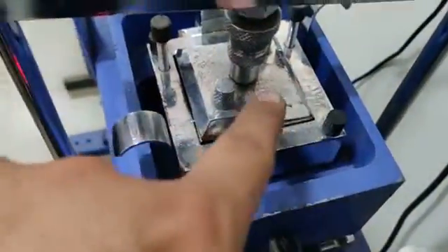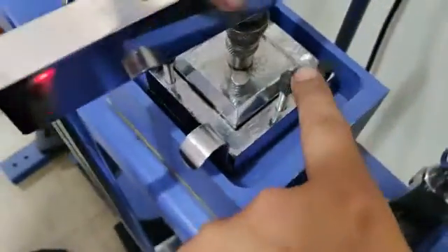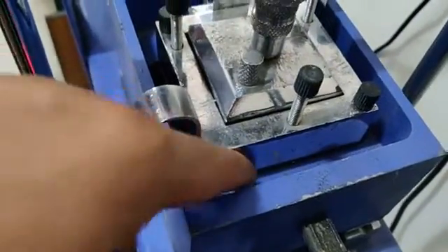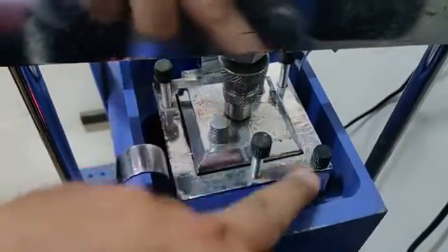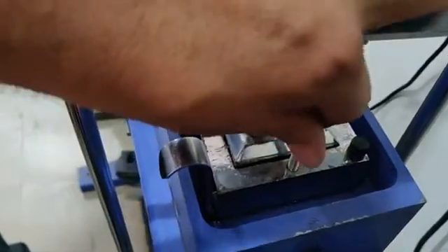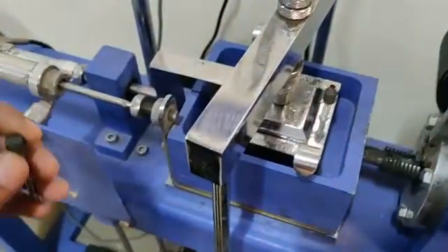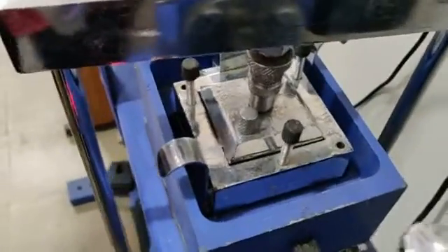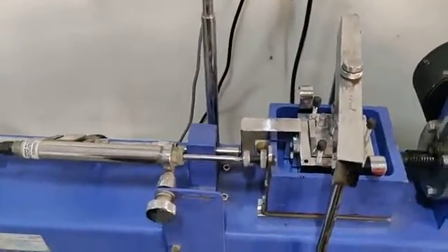As you can see, there are 3 screws here. This one is 1, this is 2, and this is 3. These screws are provided so that when we tighten the screws, the gap between these 2 plates can increase and less friction will be provided. And there are 2 screws also here. So first we will tighten these screws so that there will be a gap between the 2 plates and less friction will be applied. As you have seen, we have removed these 2 blocks which hold these 2 plates together.